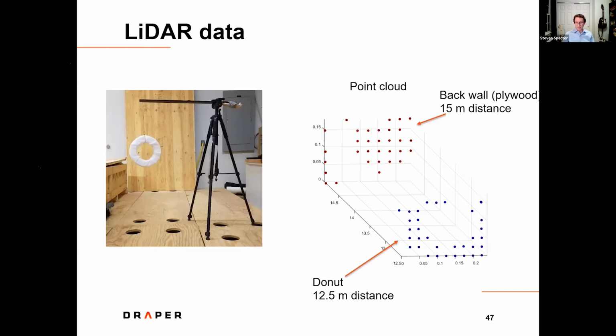And last, we did some Lidar data with this chip. It's challenging to do Lidar work with it because we didn't have fiber couplers on it, so we lose a lot of light getting light onto the chip. The way we did detection here is we just had a staring detector that saw all the reflected light everywhere. We didn't have any spatial selectivity on the detector. And it's also a very small aperture. So this is less than ideal, and yet we still got it to work.